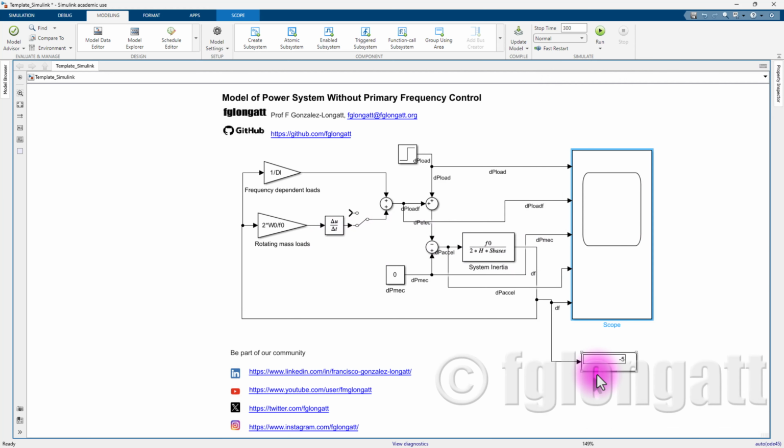If you look the numbers in a steady state, there is no change. There is no change in the steady state frequency, something that we clearly see that is happening, because in a steady state, this derivative term disappears, is not doing anything. However, this term is modifying the frequency, the rate of frequency change suddenly after the load change.